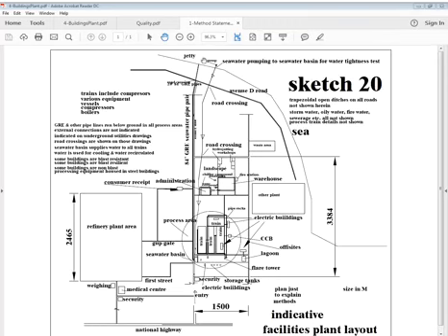And here we pump water from the sea, and this pipe is GRE sea water pipe, two pipes in one, meaning a pair, and it's not small, it is 7 feet or 84 inches pipe here, that is a twin pipe, and this comes here. Here there's a facility, this is the seawater basin here. This pipe comes here, stores water here, and this water is circulated to the whole train area for the purpose of cooling, and then the cooling water is recirculated and recirculated like that.